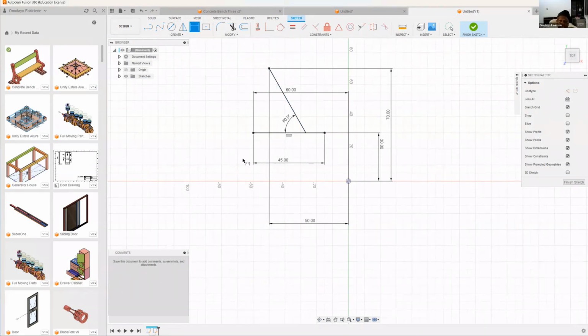Okay, again, once I select this point completely and I select the angle, everything that is supposed to be known about that is also known. So you can see I've got only two objects that I've done. One of them I constrained to be horizontal. The other I made it at 60 degrees to the previous one.